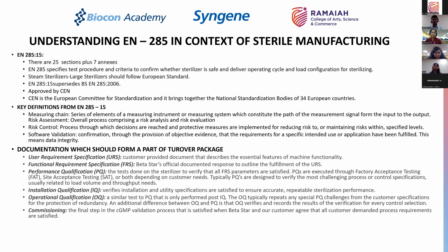Then comes an operational qualification, where you will conduct the test, where you will take some dummy loads, you will do empty sterilization cycles using your pure steam, you will check the entire control system working fine. All these tests are done during operational qualification.